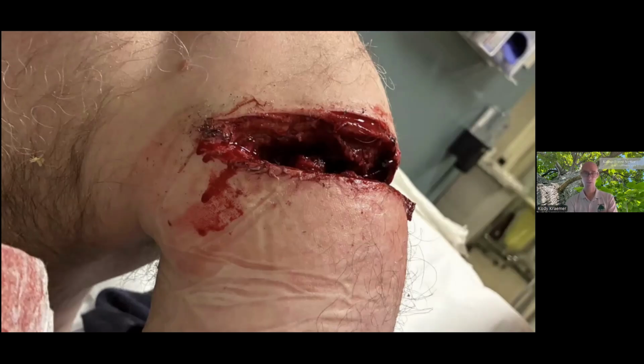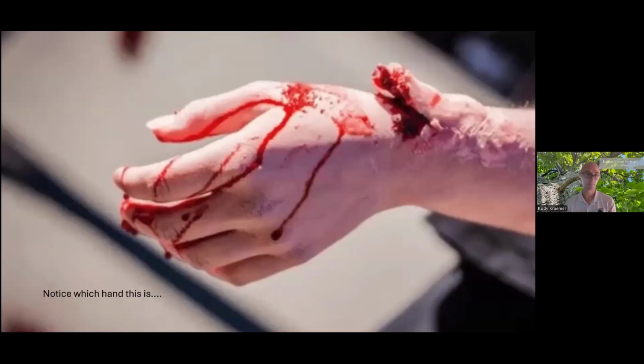This sawyer also admitted that their preference is to have low rakers or depth gauges, so they had them filed down quite a bit for an aggressive cutting chain. That can also contribute to heightened kickback potential. Okay, so a lot of factors went into this one, but pretty gruesome injury.